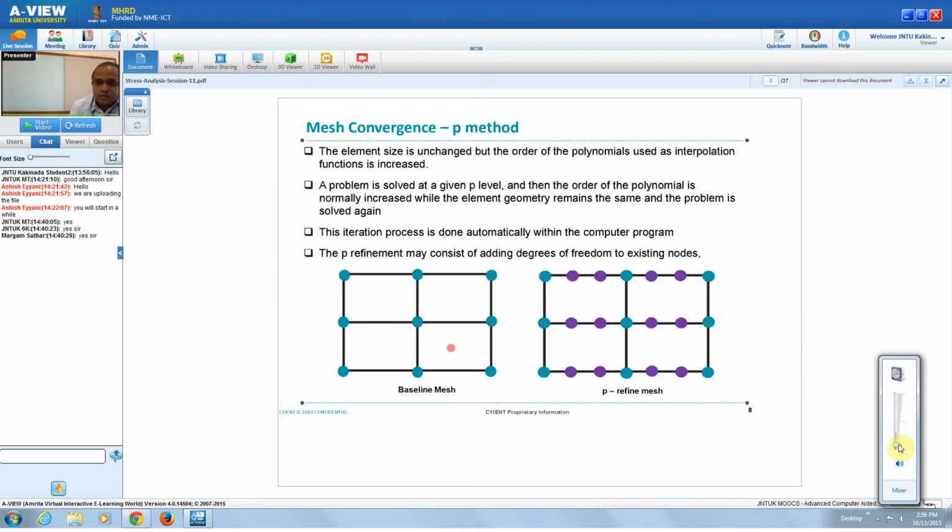This is the linear element, and here we have added two additional polynomials. Generally, in the P method, they add additional polynomials, two additional polynomials compared to the previous one. As we already studied the difference between linear and quadratic, quadratic will definitely have higher polynomials, and elements with higher polynomials will give better results, and convergence rates are much faster.